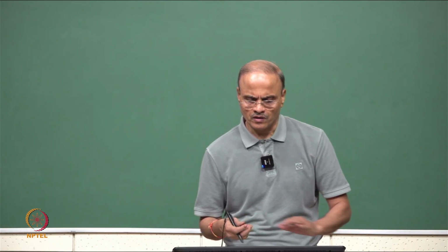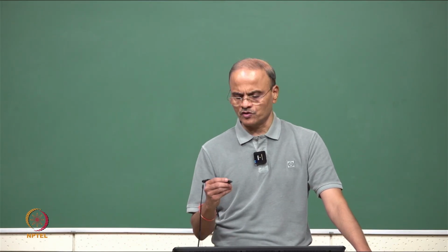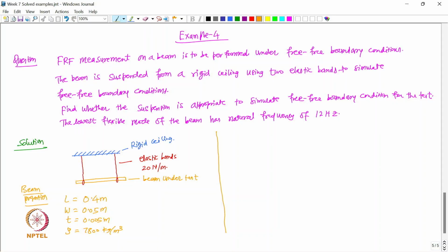So, let us determine first of all the rigid body mode natural frequency, because we have been given the first lowest flexible mode. We should determine the rigid body mode natural frequency with these suspensions.